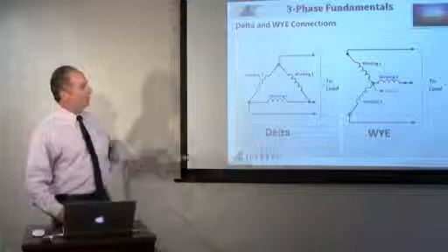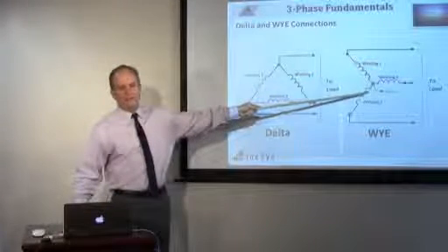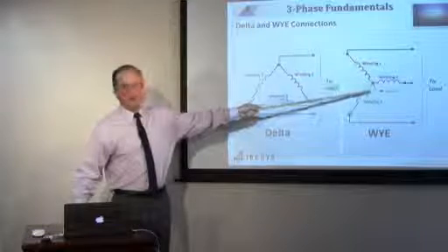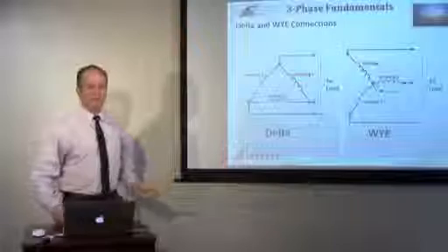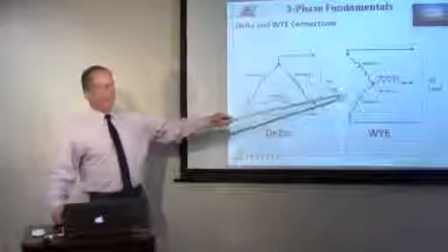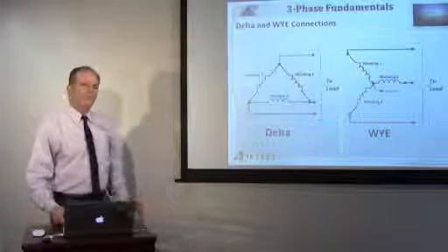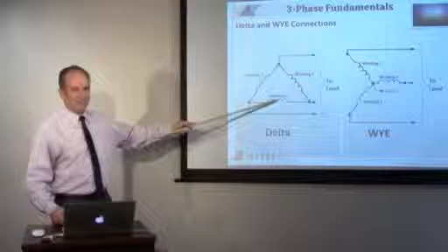Or we take 1 common wire, 1 from each winding, each coil, and form a neutral, and then the opposite ends of those windings become the output wires, if you will. And the neutral is then grounded. So we'd have a grounded neutral. Note, there is no neutral in a delta.